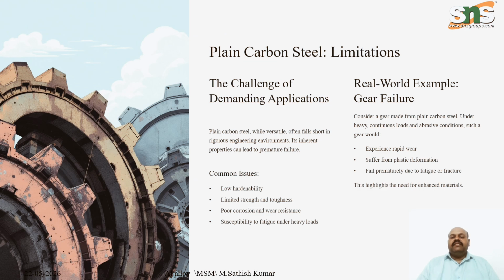So plain carbon steel, the challenges of demanding applications. We'll see plain carbon steel, while versatile, often falls short in rigorous engineering environments. Its inherent properties can lead to premature failure. So the common issues are low hardenability, limited strength and toughness, poor corrosion and wear resistance, susceptibility to fatigue under heavy loads. So the real world example is gear failure.